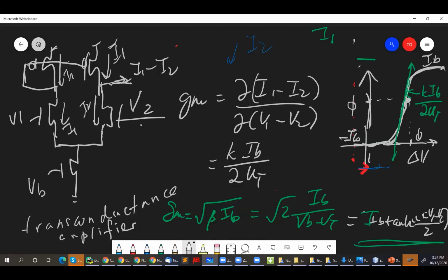Okay. There are little non-idealities that, if I go into them, take some bit of reasoning. But the first thing I want to mention here is that this circuit's not going to be perfect. If you actually look at the textbook, you'll see why it's not perfect. Ideally, you want this voltage here, if I'm going to use this voltage, to be able to swing from 0 to VDD. That would be nice if you could. And so the first thing is, do you think you can go towards VDD? This node here.